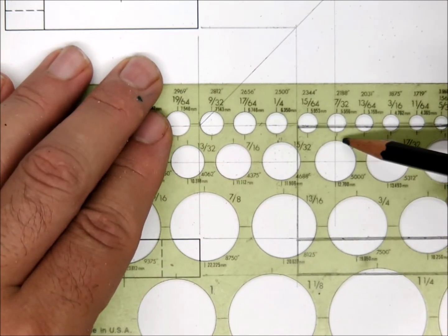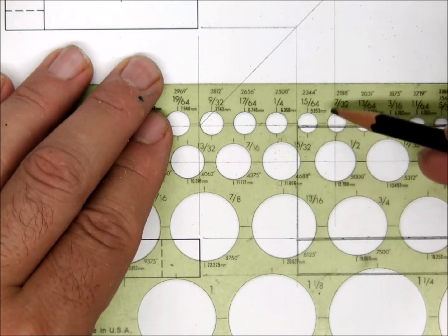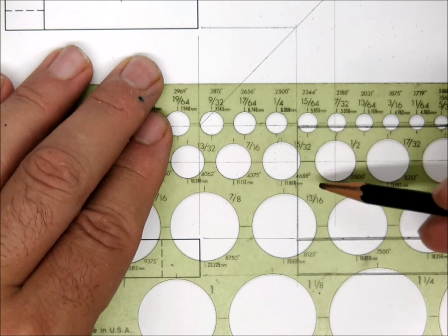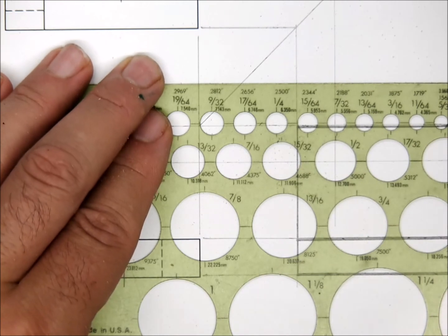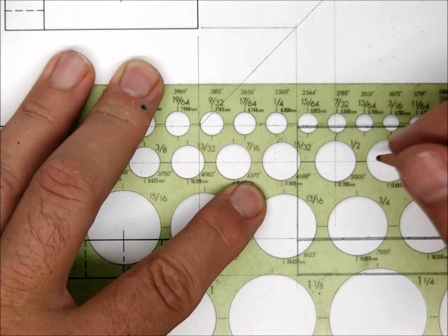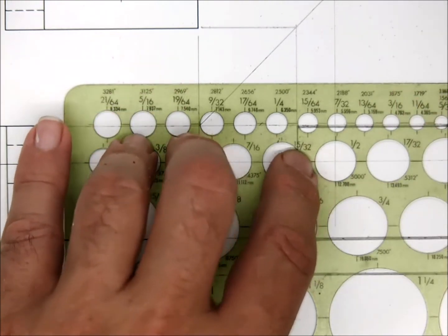The mark at the top of the circle should line up with this projected line. And then the mark here and here should line up with the projected line from the front. What you're doing is just trying to make sure that your circle is centered where it's supposed to go. So if your template looks like this with marks, that's how that'll work.